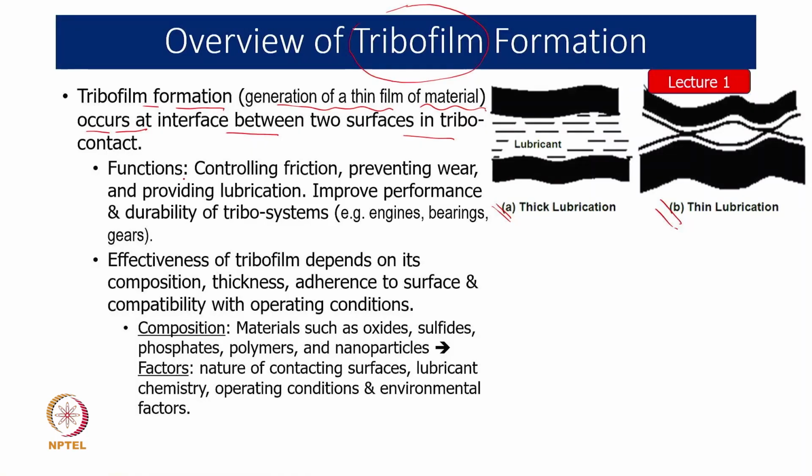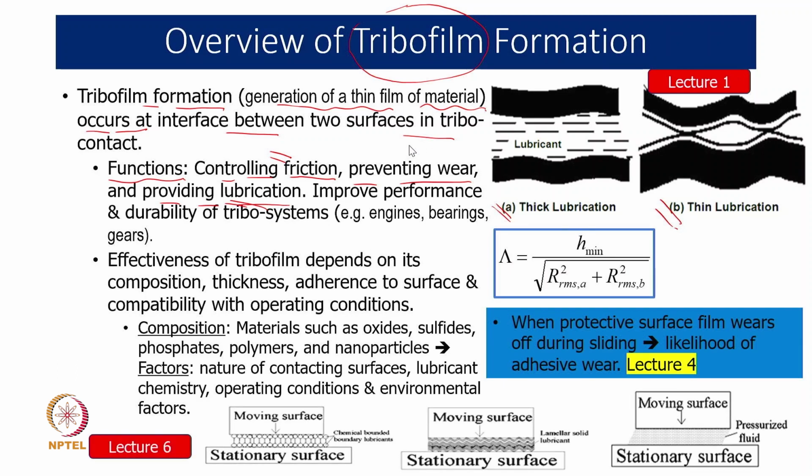What is the function of tribofilms? We say controlling friction. I can also write reducing friction, but many times we use a better word, controlling friction, preventing wear or maintaining minimum wear or eradicating the wear, and in addition providing the lubrication. So the basic purpose is lubrication, and through that we are trying to control the friction and wear. Why are we doing it? To improve the performance and durability of the tribo systems.